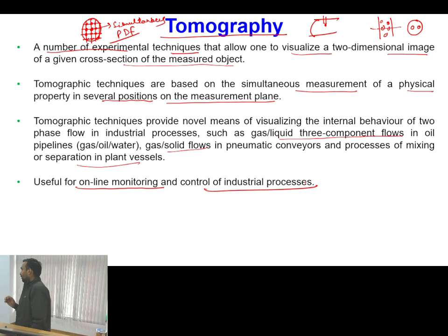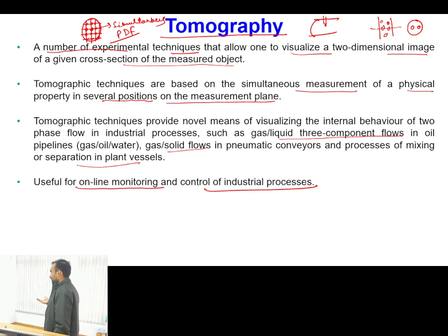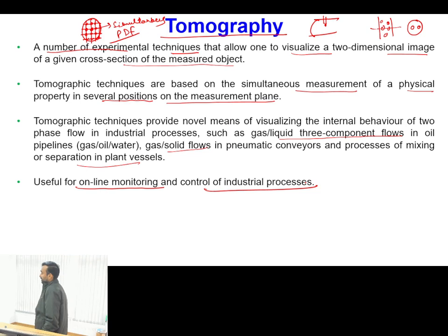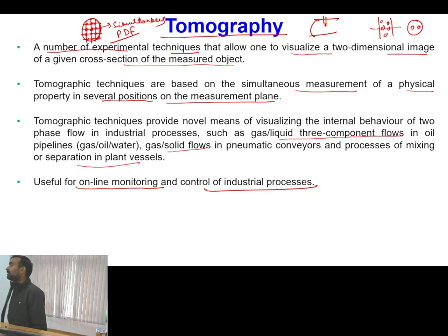After repairing the fault, once again when you start it, reaching a temperature of 700 or 800 degrees Celsius from the ambient temperature will again take a significant amount of time. So if you have to stop a coal-based thermal power plant and then start it again, it may take a time period in the range of 15 days to 1 month because of its thermal inertia.